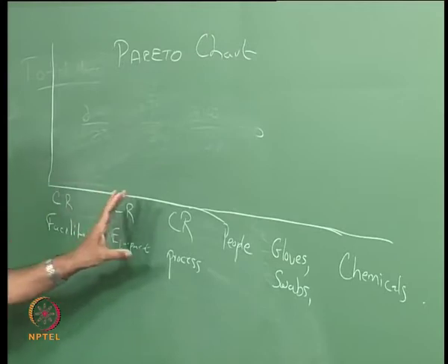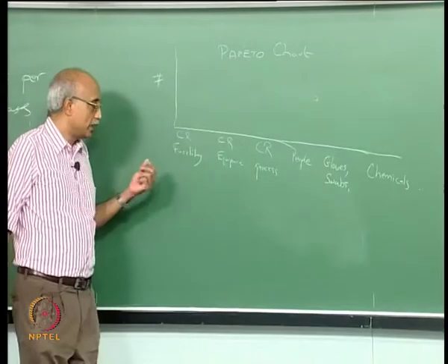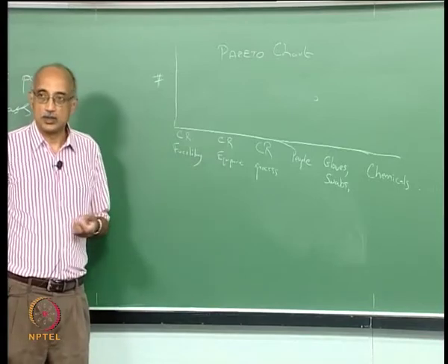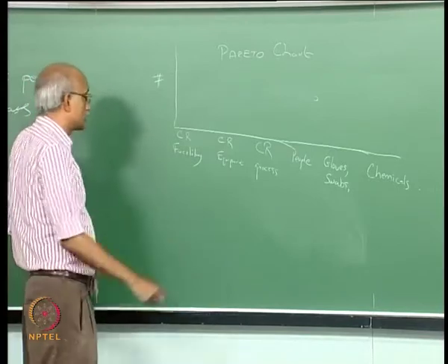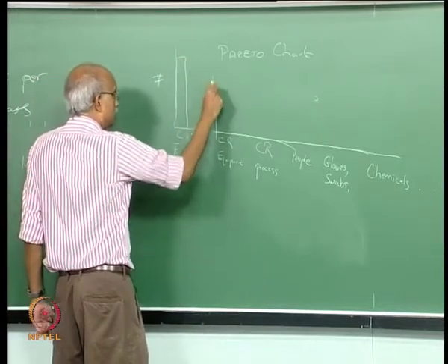You can actually critically analyze and identify possible sources of particles inside a clean room, and then you actually assess the magnitude of each. So you have to have a way of measuring the number. How many particles are contributed by the facility, how many are contributed by the equipment, and so on. If you can do that quantification, then you can actually develop a bar chart.